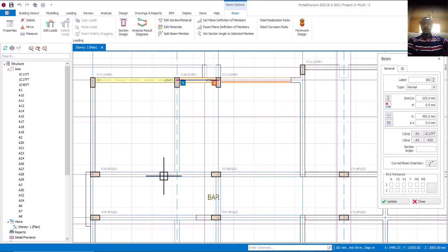That's fine. So I also come to this other side too and do the same thing. Right click and click on offset. Where is my offset? Click on this. Let me see if I can locate the center from here. Okay, I cannot locate the center, but I can put it here. That's fine. So I can now click on this, right click and click on offset, and come to this other side, press my F2, 225, am I correct? Enter. Perfect. Then click on this one, then delete.